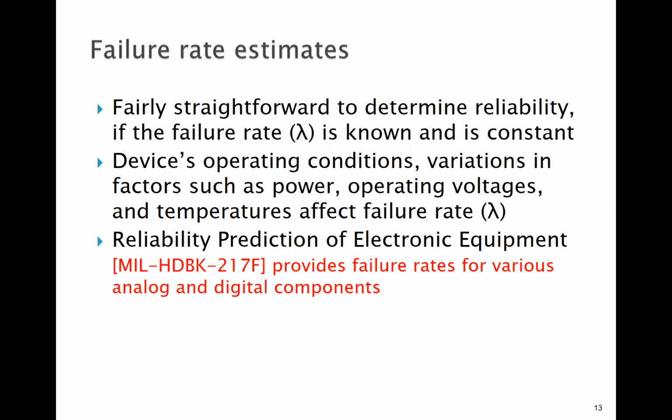So then, failure rate estimates. Here, as you might see, failure rate, lambda, is quite critical. So how to determine this lambda is quite a challenging problem. There are too many parameters: operating conditions, variations in power, voltage, temperature, all affect the failure rate of an electronic.